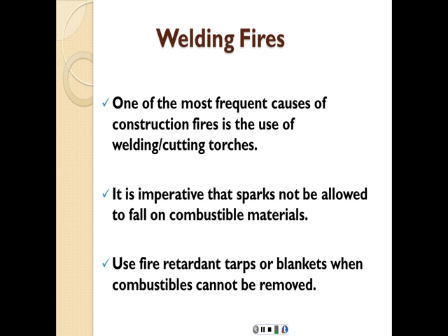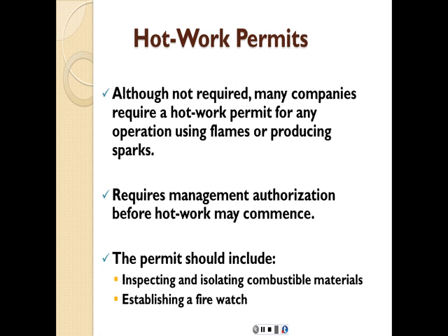Welding fires. One of the most frequent causes of construction fires is the use of welding or cutting torches. The issue is that there's going to be some residual heat even after you're done with the welding. The metal itself might still be hot. It's imperative that sparks not be allowed to fall on combustible materials. Sparks are one source of ignition. Use fire retardant tarps or blankets when combustibles cannot be removed.